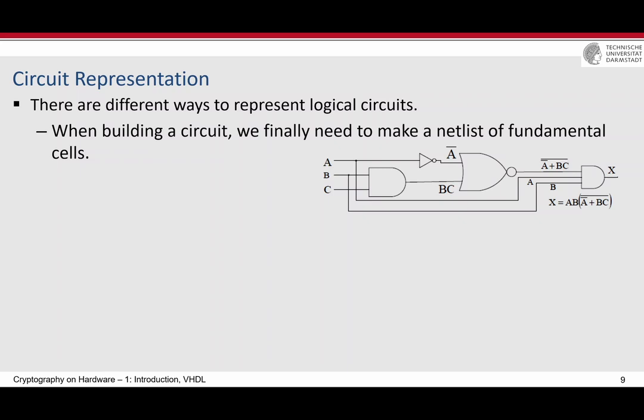In ASIC, each of them is inside the library that you have, because for every ASIC design that you want to build or fabricate, you have to select the library. Inside the library, it is defined how they are, the shape of the AND gate, and how the transistors are connected together to build an AND gate. This is the ASIC design. And then you need to really geometrically put this together, not manually, but with some tools, to build the circuit.